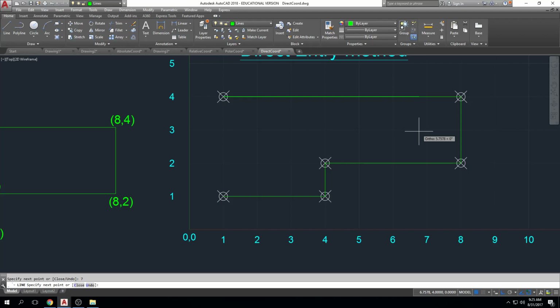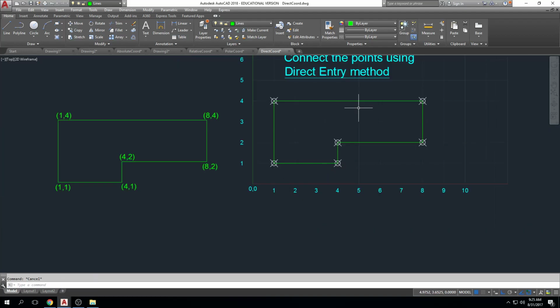So this is pretty easy because there's no positive negative, okay? So here I'm going to type 1, 2, 3, -3, or not -3, sorry, 3, because by moving my mouse in that direction, I have shown AutoCAD I want to go -3, so I just type 3 and it moves in that direction. Okay, so this is going to be the way by and far that you'll be drawing things, right? You'll open up a drawing, you will start where you want it to start, and then you'll just start drawing away. Okay, now so we've got absolute, relative, polar, direct entry coordinates.